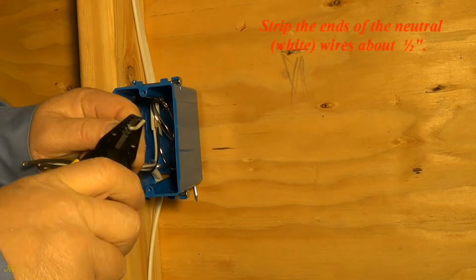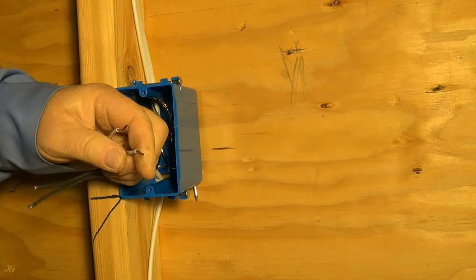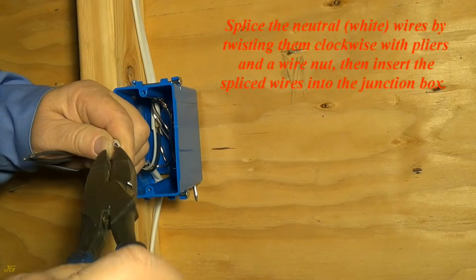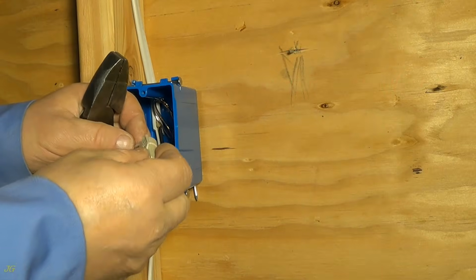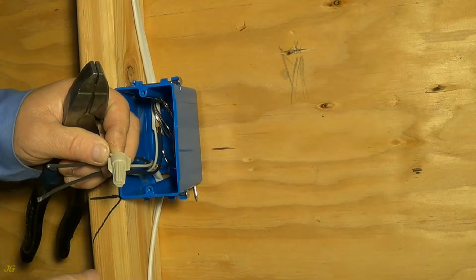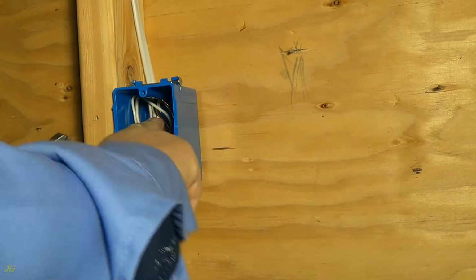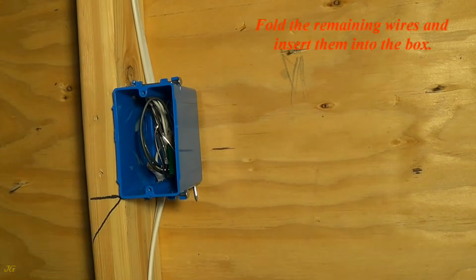Strip the ends of the neutral, white, wires about 1/2 inch. Splice the neutral, white, wires by twisting them clockwise with pliers and a wire nut, then insert the spliced wires into the junction box. Fold the remaining wires and insert them into the box.